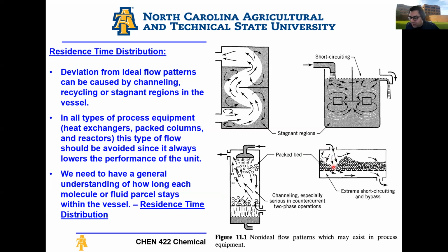And then the other thing here is, again, you have short circuiting. If I have a packed bed and I introduce gas, the gas will never reach the solids which are piled here, right? It will just react at the surface and then exit, or maybe it will create a flow path and all the gas will zip through it. So I'm not using any of my solid catalysts, etc.